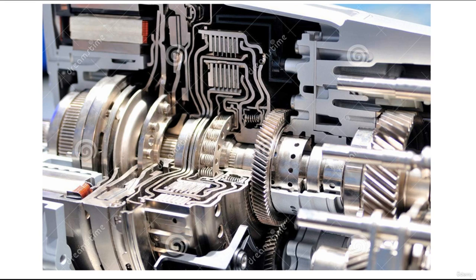Until recently, all automatic transmissions were controlled by hydraulics only. However, most systems now feature computer-controlled operation of the torque converter and the transmission, based on input data supplied by electronic sensors and switches. The computer sets the torque converter's operating mode, controls the transmission shifting sequence, and in some cases regulates transmission oil pressure.